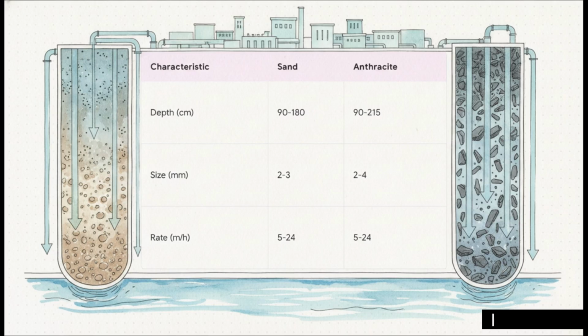And with effective particle sizes sitting in the 2 to 4 millimeter range, you can achieve filtration rates of up to 24 meters per hour. These are massive, continuous systems that are heavily utilized in municipal water treatment.